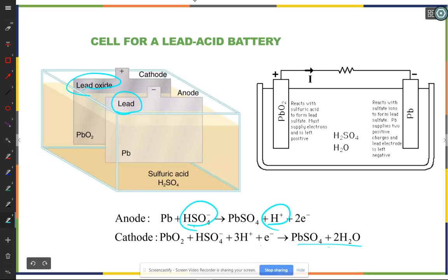But at one, each reaction absorbed an electron. At the other one, each reaction produced 2 electrons. And so what you're going to do with these two coupled reactions is the reaction will go until you reach a balance between the electric charge and the energy required to make the reaction go. And so you end up with a positive and a negative electrode called the cathode and the anode. If you connect something to the battery, you'll have electrons fly away from the negative, electrons pulled into the positive.